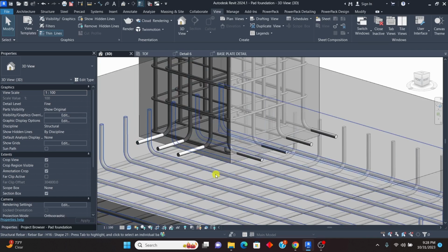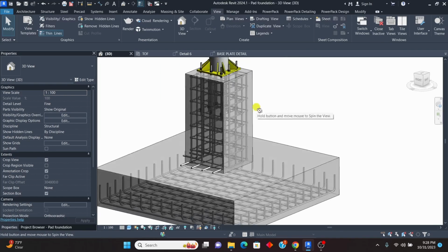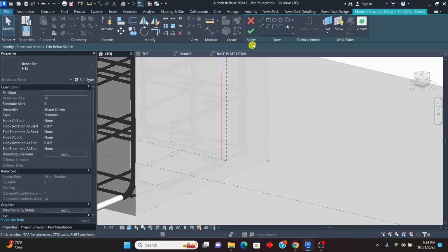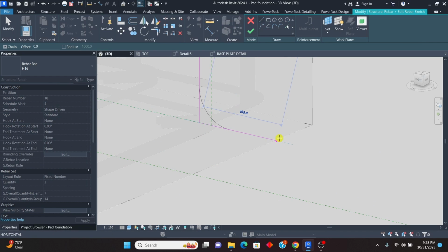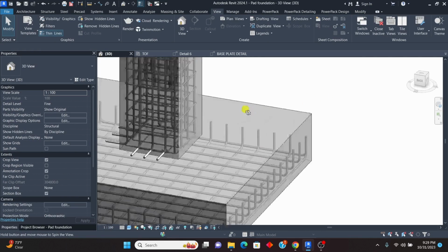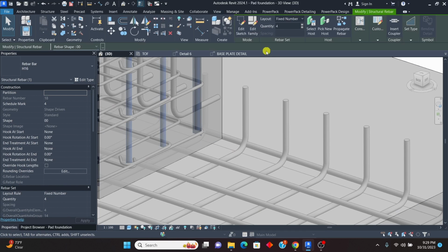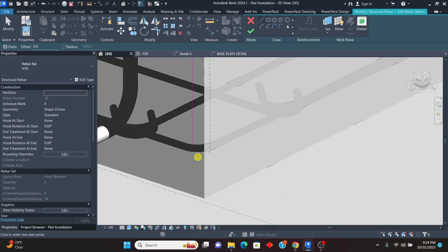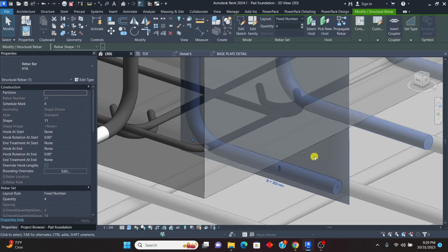Now I'll need to drag these bars up to the bottom. Don't have to worry about this. Actually, I should have dragged them first. So I'll select there once again, then edit sketch. Okay, then I'll click on that one and just pick it from there. I still want to use the same 200, enter, right click cancel, just like that, then finish. I'm sure I still have the last bar there, maybe this side. Select it, edit from there. Okay, we have it here. Then I'll pick the line and pick the point there, then simply drag it there, then 200 and enter from there, then finish from the green check mark.